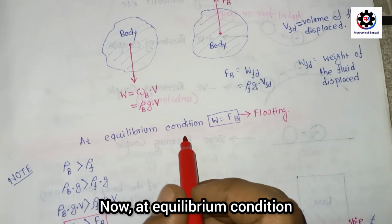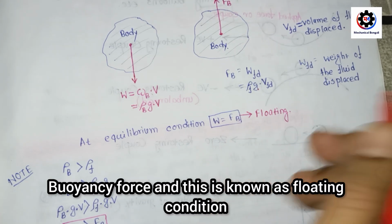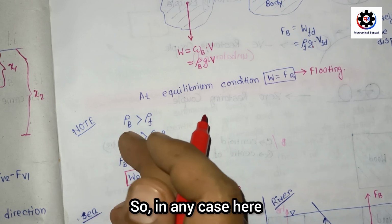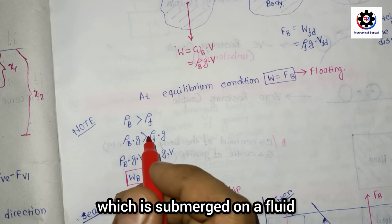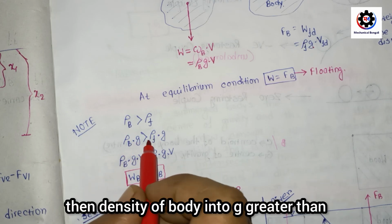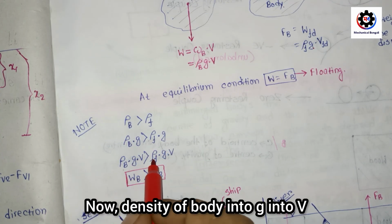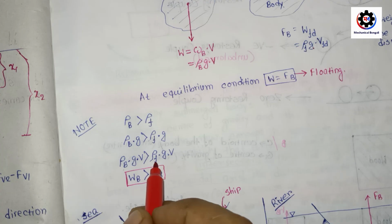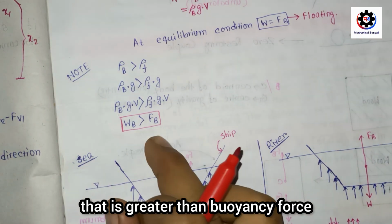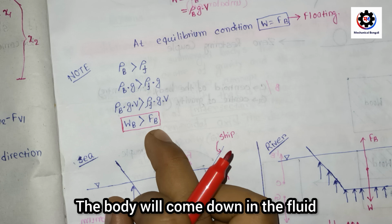Now at equilibrium condition, the weight of the body is equal to the buoyancy force, and this is known as the floating condition. Now suppose the density of the body is greater than the density of the fluid. If the density of the body submerged in a fluid is greater than the density of the fluid, then density of body into g is greater than density of fluid into g. Just multiply it on both sides. Now density of body into g into V is greater than density of fluid into g into V. So from here, the weight of the body is greater than the buoyancy force. Okay, so if the weight of the body is greater than the buoyancy force, the body will go down in the fluid.